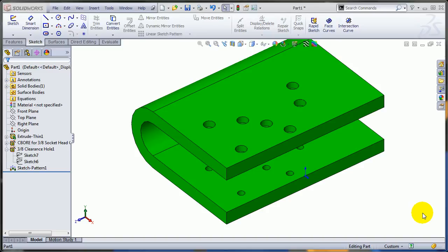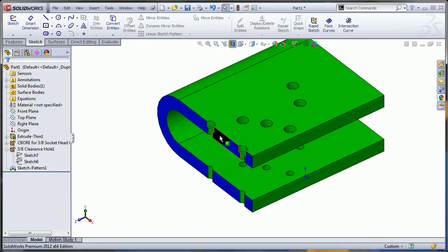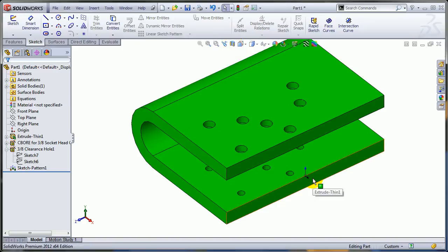In this series, we'll try to establish a workflow for using something similar to the whole series at the assembly level, but this time at the part level. As you know, in the assembly level, you can have a counterbore on the top plate from a sandwich of plates, maybe a clearance hole in the middle ones, and a threaded hole or another clearance hole right at the bottom. You cannot do that directly at the part level, but there are workarounds. So let's see how we can do that.